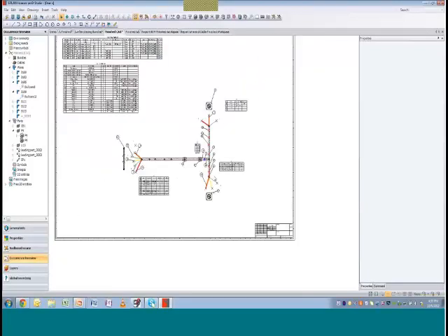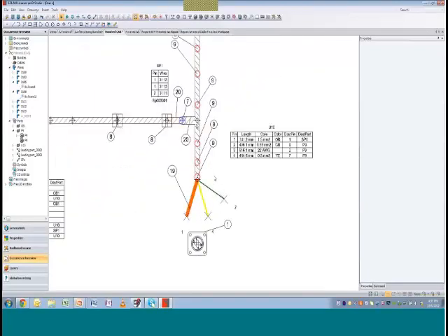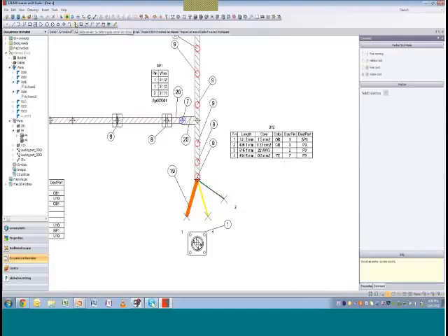Here with our branches, you have some tools up here to move and modify how your harness is going to be laid out for that nail board. So you can do some manipulating before you actually send this out to manufacturing.